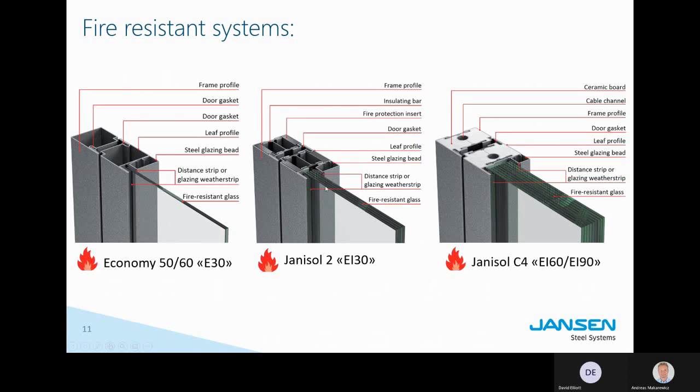The glass itself on the EI class is a multi-layer glass, and between the glass layers you will have a gel, a cooling gel or liquid that is not visible, but once the fire hits the glass, it starts reacting. It becomes opaque, and the glass actually breaks, and the gel or the liquid evaporates. And this is the cooling action of the element, of the glass.